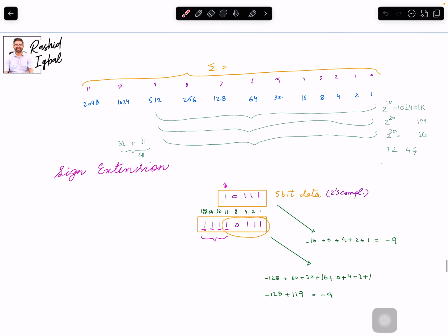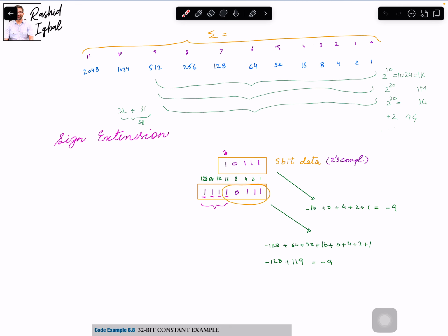All right, then the concept of sign extension. If we have a 5-bit line and the number there is negative, with a 1 at the top, and you want to have an 8-bit line, how do you fill it, with 0 or 1? In sign extension you have to replicate your sign bit, but the number stays the same.